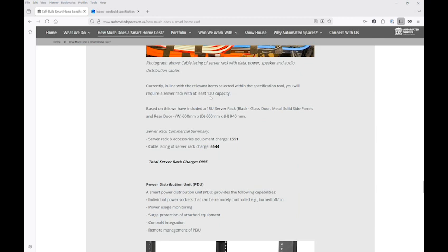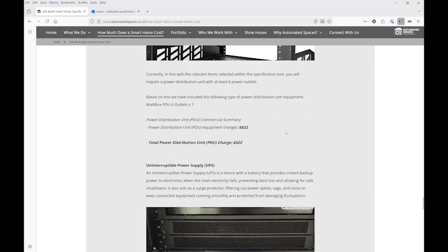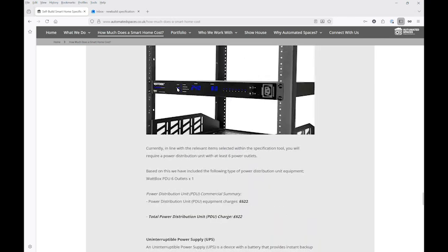Here you can see the size, so we've automatically worked out that we needed a 13U rack, so we've specified U of 15, which is the next size up, and here you can see the dimensions for that rack, so that rack is under 1 meter high. We'd also then work out the power requirements, so how much power we need, and we have here smart, what we call PDUs, so power distribution units.